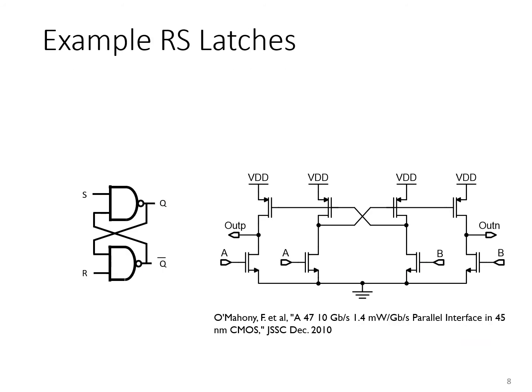Now the outputs of the dynamic comparators that we've discussed so far accept as inputs differential voltage VI and a clock. And as the clock alternates between high and low, the latch alternates between a reset stage and a regeneration stage.